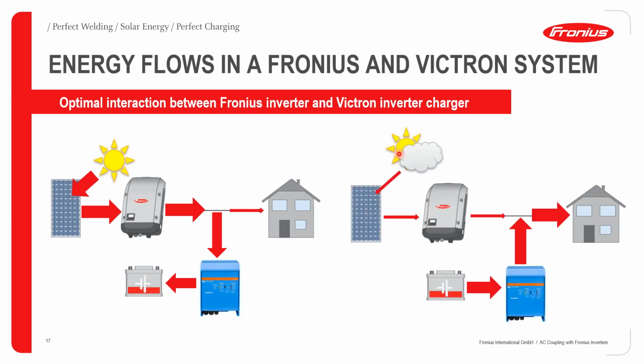If there is a bit of cloud cover or irradiation levels change, and therefore the PV array reduces the amount of power it's giving to the inverter on the DC side, then the battery inverter from the battery reserves must be able to fill the gap between what is being generated by the PV inverter and what the load actually requires. So therefore, the total amount of power fed to the loads equals production by the PV inverter plus the supplement from the battery inverter.